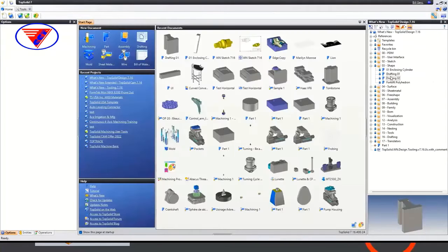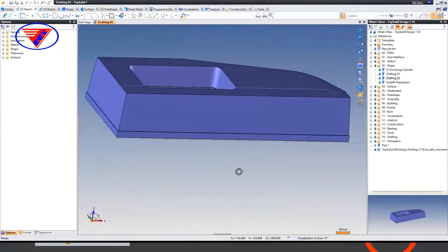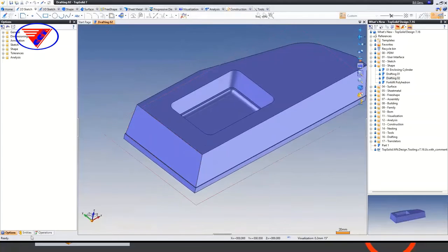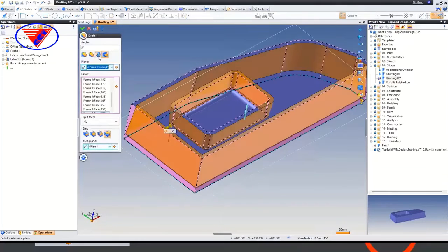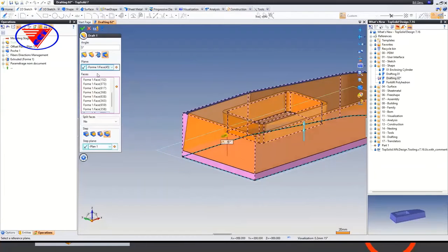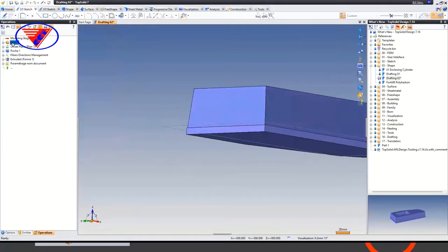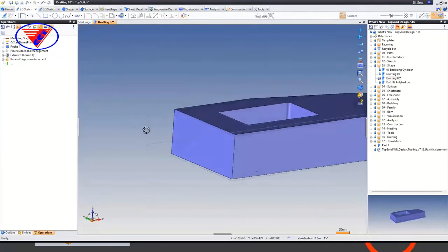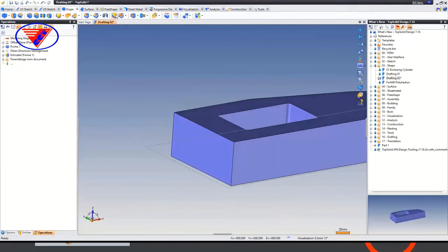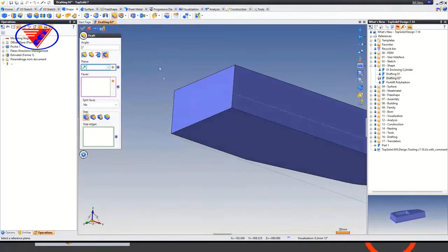Next, let's look at another sample. So in this case, I have a part, right? And if I go look at my draft option, I'm choosing this bottom face, and here, I'm sorry, let me delete this. I think I left it on there from practicing. So let's go here, and we're going to use draft with step. My reference face is that one.